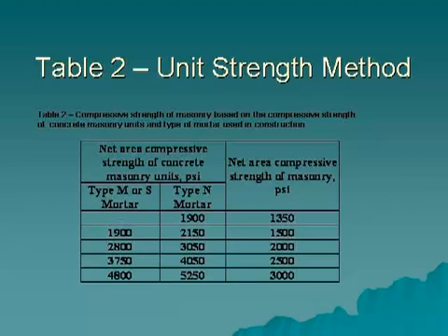To increase our awareness of quality assurance, consider the following. Owners can expect block to be tested for compressive strength, absorption, density, and moisture content to prevent drying shrinkage. Moisture content is controlled at the job site by the contractor. How often should block be tested during construction?